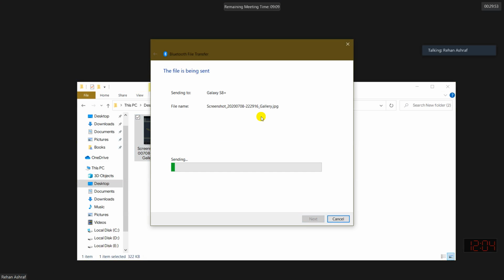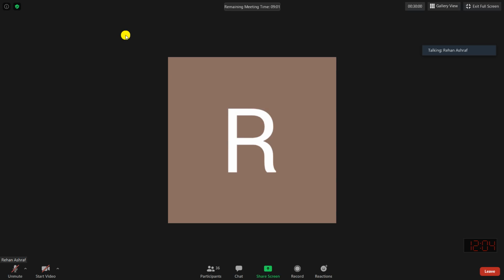Okay, answer to roll number 90: what will be appropriate height and width of the beam? Width of the beam is basically equal to the width of the member it is supporting. If it isn't supporting any member, you can provide a width of 9 inches. 9 inches is the most common width of beam. What about the drop? A drop of 9 inches is fine.